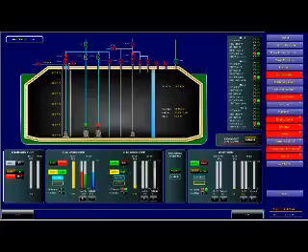This one is not coming on auto. Leave it on manual then. Because the preset levels are high, set it to low level. There is very high discharge pressure. Can you check why it is like that? Check the lines. Is the cargo going out? Yes, the cargo is going out.